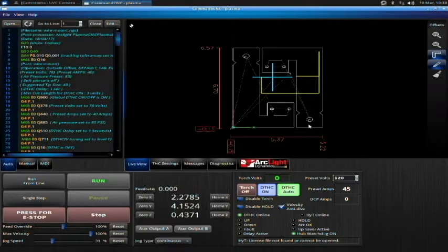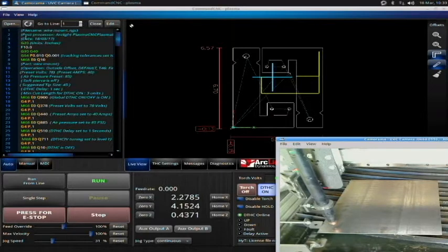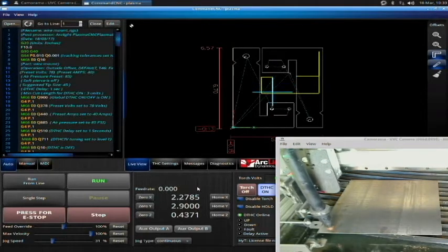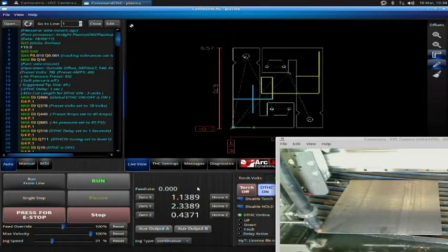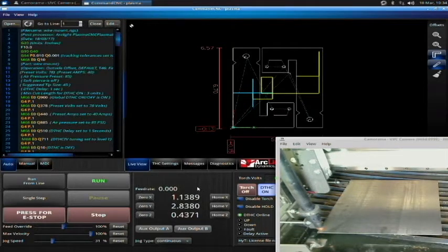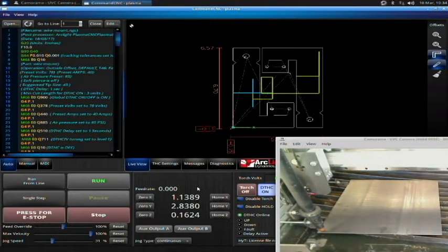Okay. Because I cannot, if I pull up the camera again, as you see, get all the way down to the machine 0. I'll be off my plate. So that's not correct. So if I'm going to start my cut, say here, right on the corner of this plate for this part. So one thing, when you're starting your cuts, you always want to inset a little bit from the edge.